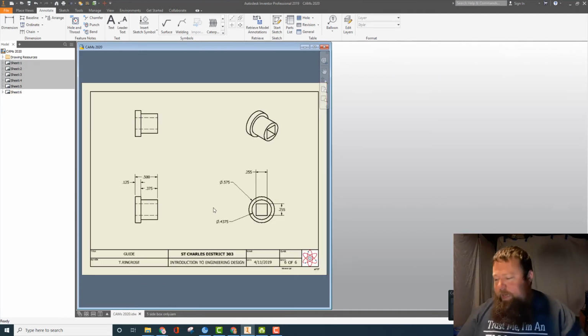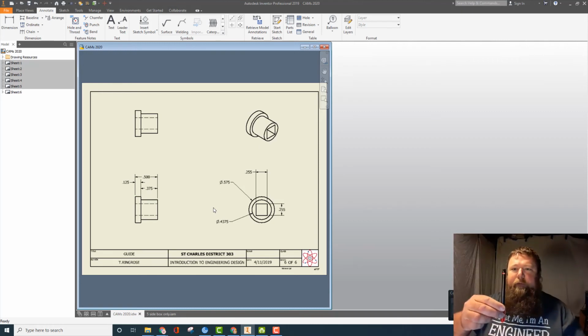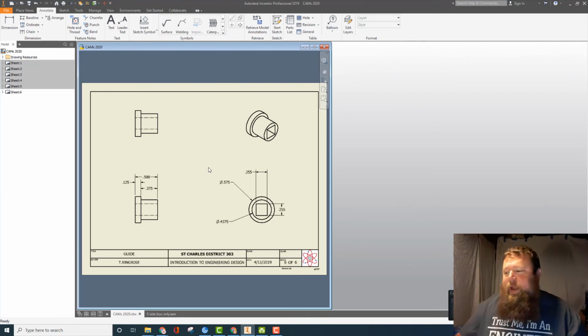Last up is what we call our guide. So the tricky thing when we deal with these cams is that the follower is moving up and down, and it's going through an opening, but we need to make sure that there's not room for that to flop around and go off to the side and get all kilter. So what we do is we insert these guides here that allow that to stay straight up and down, keep it true. So what's also called a bushing, depending on what industry you're working in. And again, it just keeps things aligned so the bores stay centered.